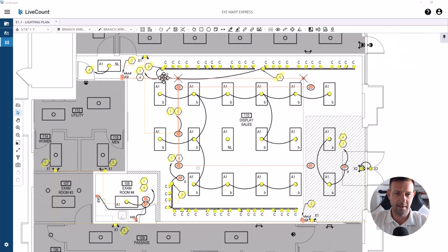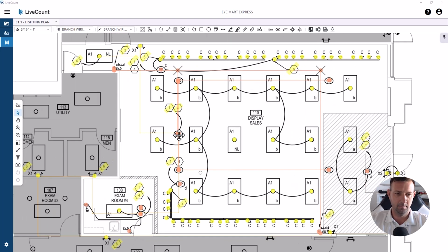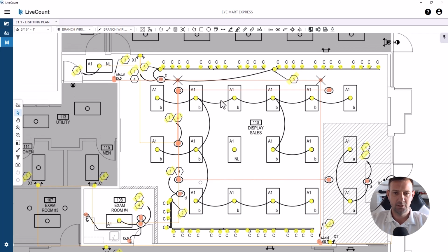They've got it designed as if they hit a power pack and then an aux sensor. So this one controller controls everything. The one controller, if you remember, we've got a specialty cable that goes from the controller to the keypads, and then we've got a 3 conductor that goes from the controller to each aux sensor. So that'll be each zone, and then the 120 volt loads will be MC out of the controller to the track light, and then luminary cable out to the dimming loads for the A1 fixtures. So anyway, interesting, kind of.